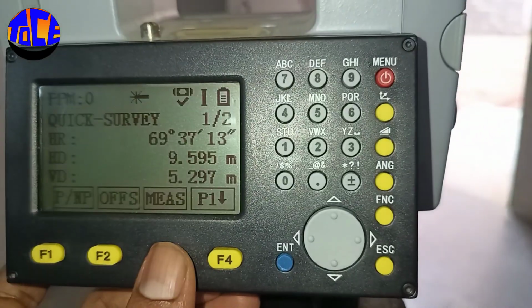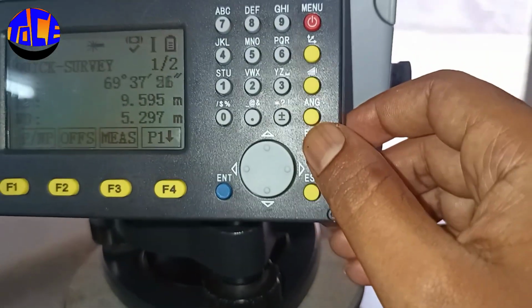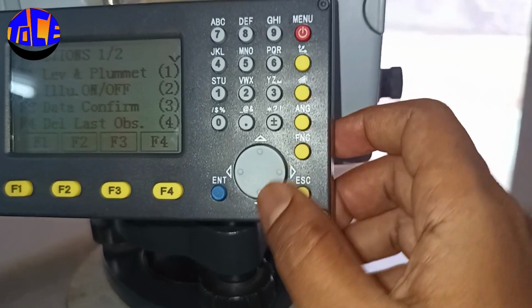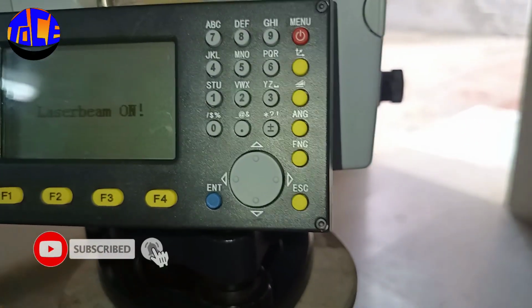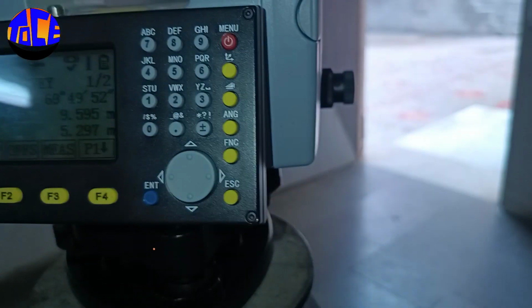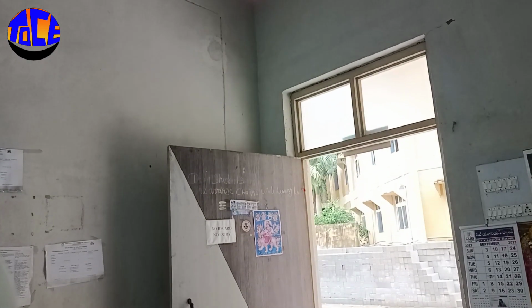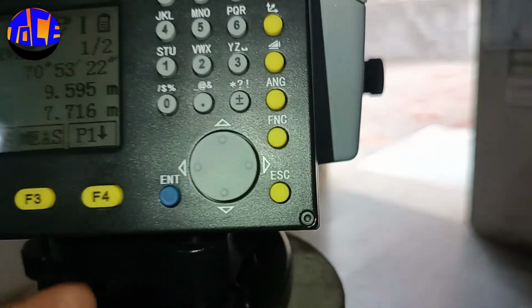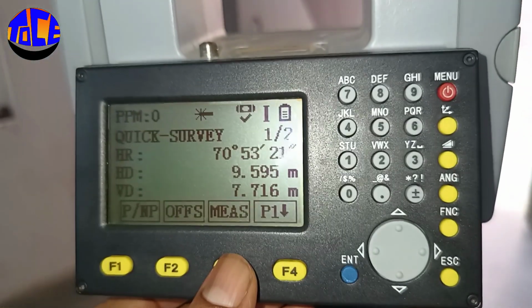Just click measure. For your convenience, let me turn on the laser beam so that you can see where I am targeting. Yeah, F1. So in the functions, hit the down button, and in F1 you will have the laser beam. There, yeah, that corner, you can see that corner I'm targeting. Now let us measure the horizontal distance and vertical distance. Just hit measure.